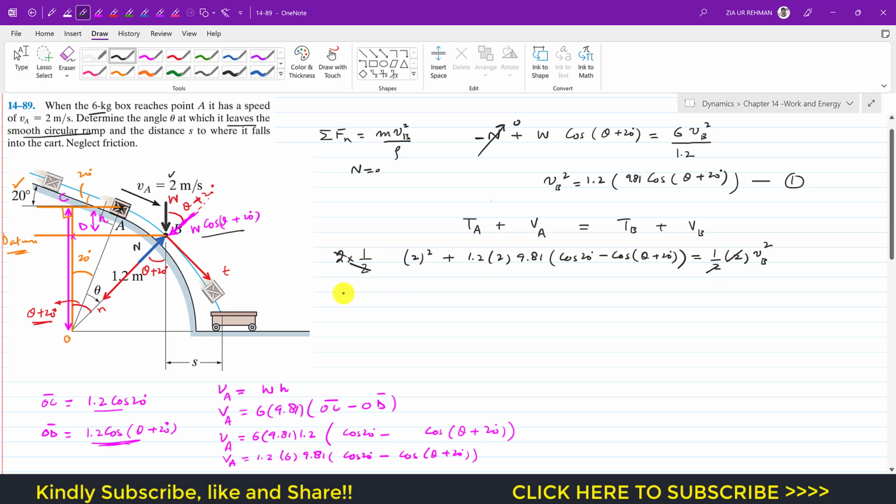So now we are left with 2 square, which is 4, plus 2 times 1.2 into 9.81 cos of 20 degrees, and similarly minus 2 into 1.2 into 9.81 cos of theta plus 20 degrees, and this will be equal to Vb square.